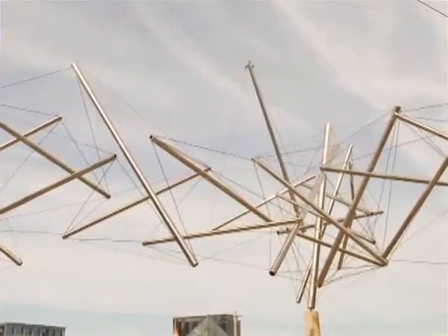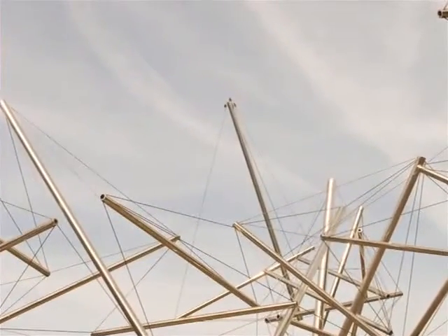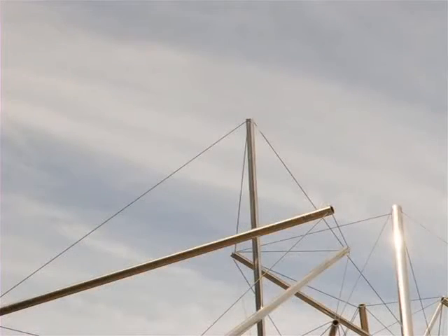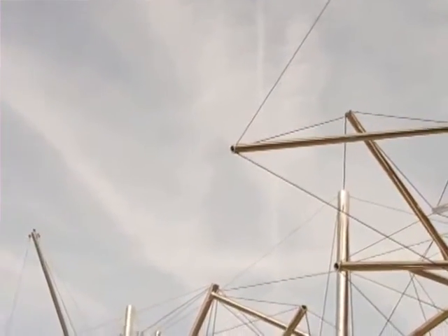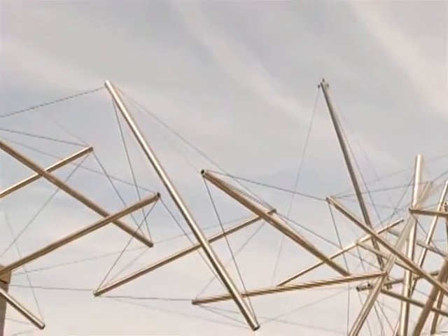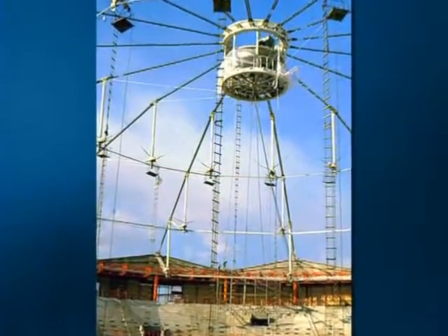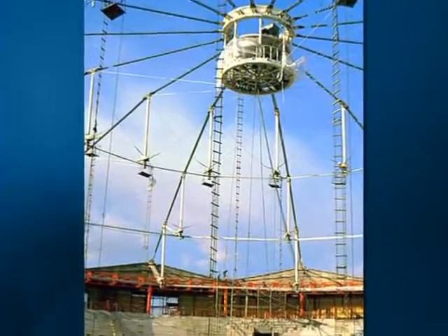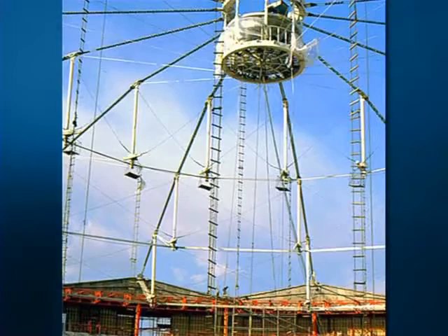What makes tensegrity work is that there have to be at least 3 tension members connected to the end of each compression strut. These 3 tension forces then keep the end of the strut fixed in its position in space, and if both ends of every strut are fixed in this way, then the entire framework becomes rigid. Geiger's tension dome follows this same principle, as you can see if you look very carefully in this photo. But in practice, it's a bit easier to see it on our model.